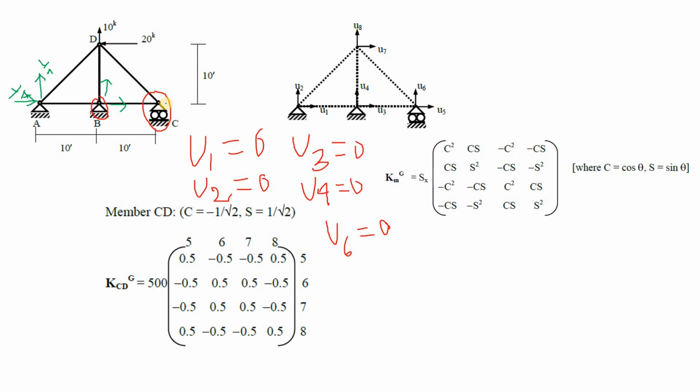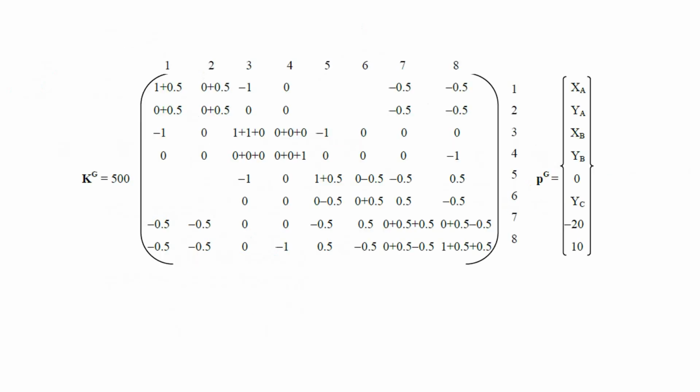The possibility of a force in the horizontal direction for C is not possible since it is a roller, so there is only going to be one force possibility, YC, and XC is going to be 0 because there is no possibility there. So that is why we have XA, YA, XB, YB, and this 0 is actually XC.